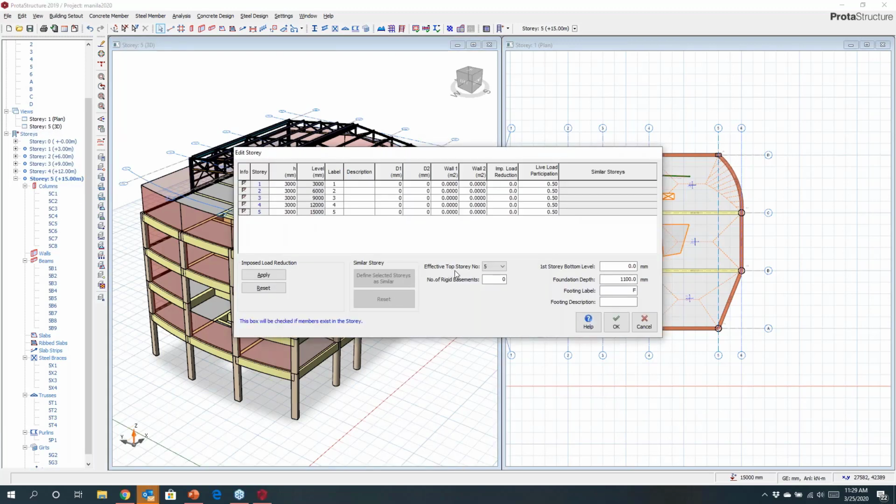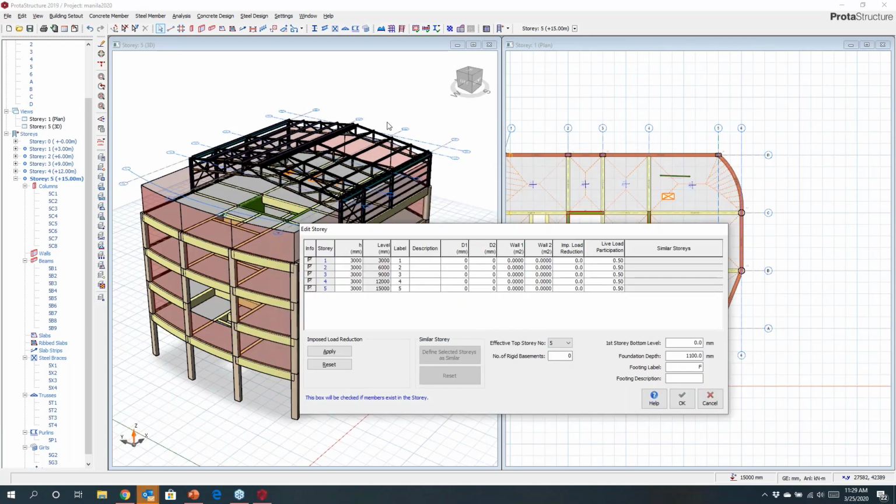Now I've actually got a model where I have a very flexible structure at the top, and I've got my concrete frame below. Now I may want to just not consider the flexible structure at the top as part of my irregularity checks. I know that this is going to cause extreme stiffness warnings. I may want to remove that. It's not removed from the analysis. The analysis is still considering everything in here. We can do things like that.